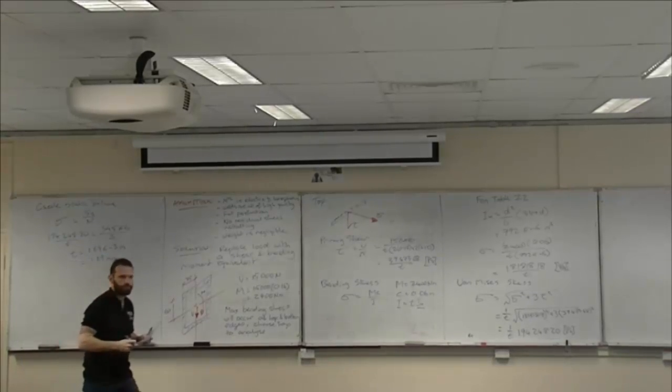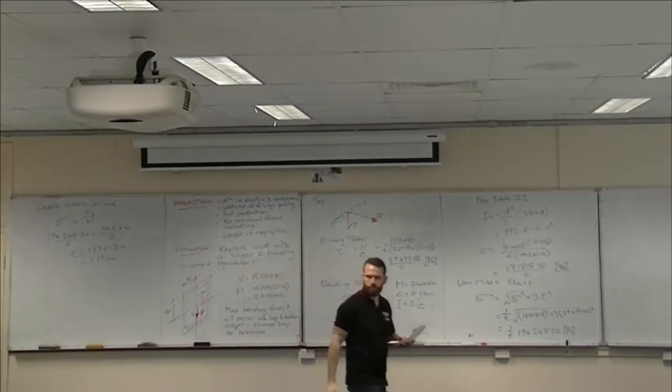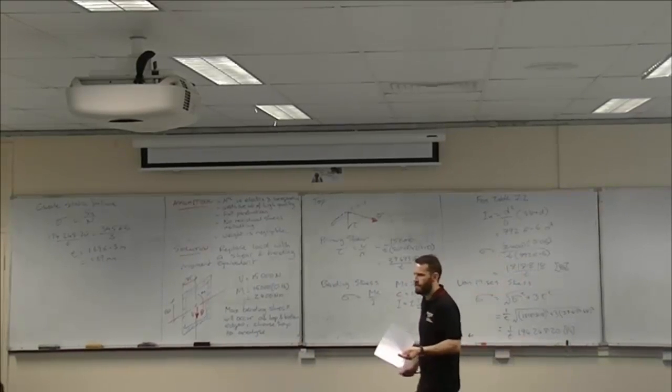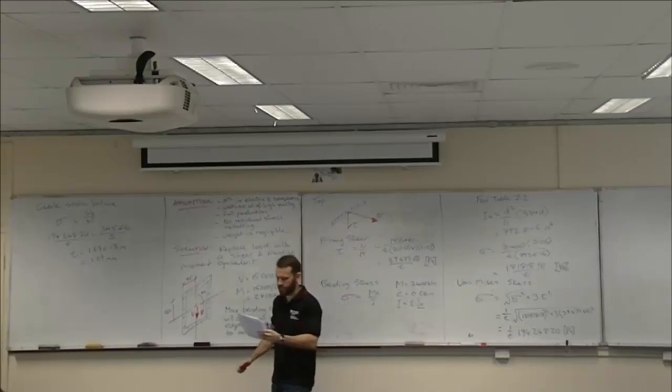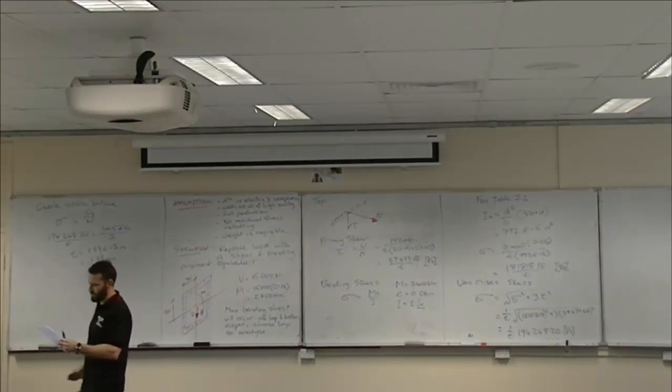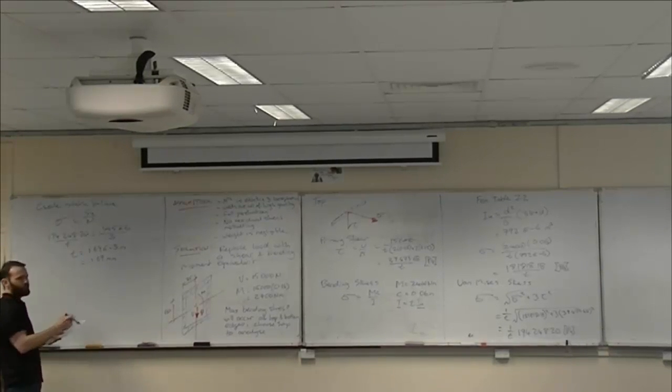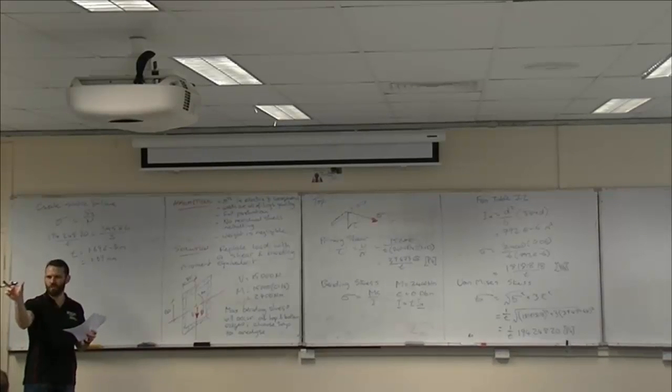Am I done? What's the question asked for? Size of the weld, which is h length. Okay. Should h be bigger or smaller than t? Bigger. There you go. H should always be bigger because that's the bottom of the triangle, whereas T is always associated with the smallest area, because the smallest area gives us higher stress.